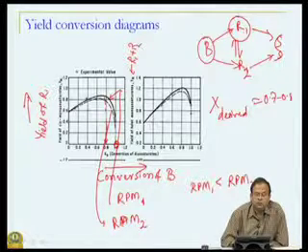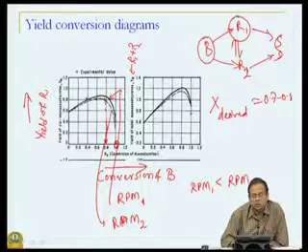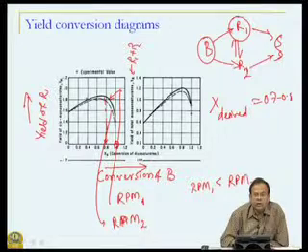While the first part of this is true, that is, if you agitate more, you will have better mass transfer between the gas phase, that is hydrogen, and the liquid, and you will have higher concentrations of hydrogen in the liquid. But as we saw a few minutes back, in order to get higher selectivity or yield of R1 over R2, we need lower hydrogen concentration, because that selectivity was inversely proportional to hydrogen concentration. So, lower RPM, lower hydrogen concentration, higher is the selectivity.